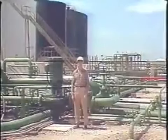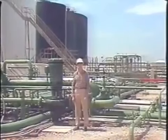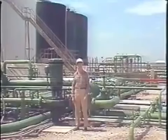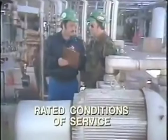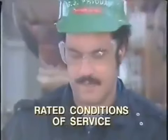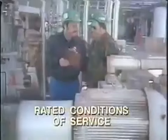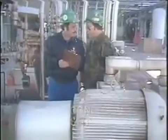Now, let's take a look at pump operation, startup, and shutdown. Centrifugal pumps are usually selected for a given flow capacity and total head, or pressure capacity, when operating at a given speed. These conditions are called the rated conditions of service and are the conditions under which the pump should be operated for peak efficiency. If operated under conditions other than its rated conditions for long periods, the pump will be damaged and maintenance costs will rise.